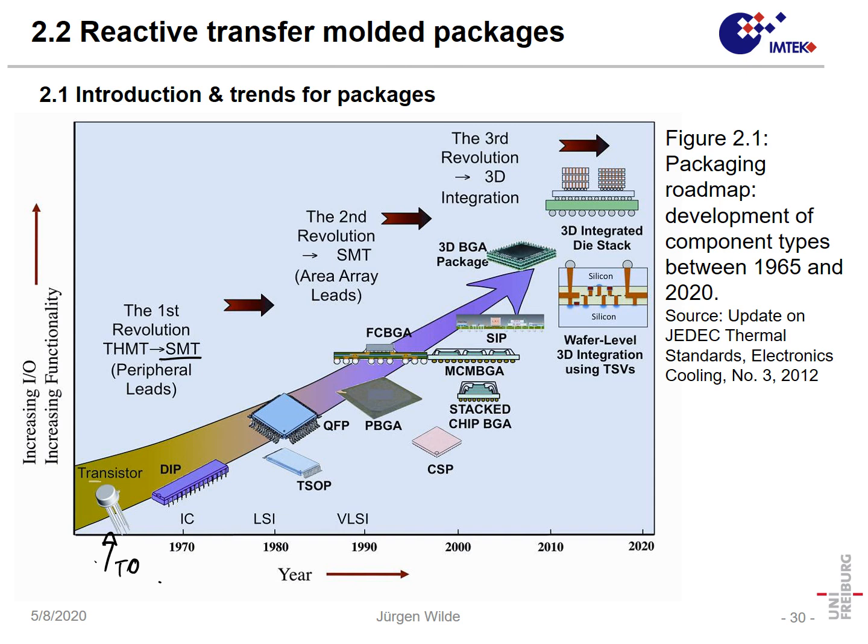On the other hand, the requirements to have larger and larger I/O numbers led to the invention of the ball grid array. We must say before that we had the so-called pin grid array, so the pins were removed, the balls were installed, and then we had such ball grid arrays. In that case, it's a flip chip ball grid array because the chip is mounted by flip chip technology on the ball.